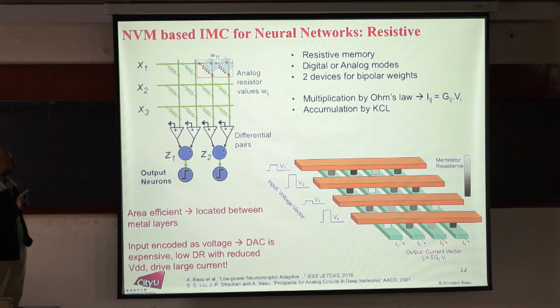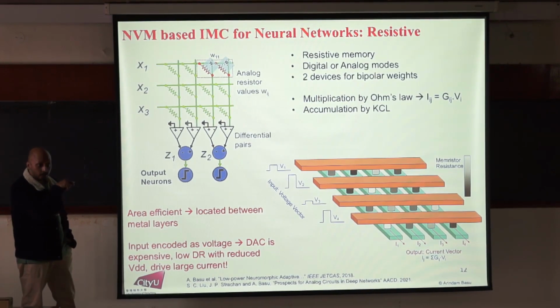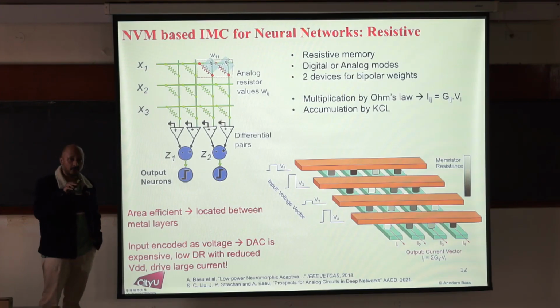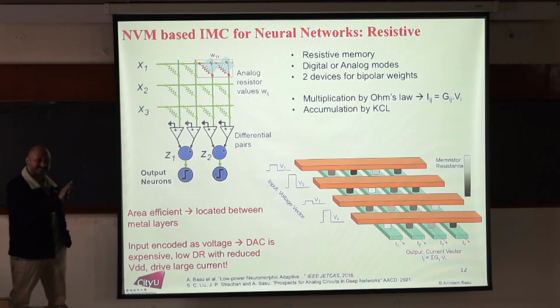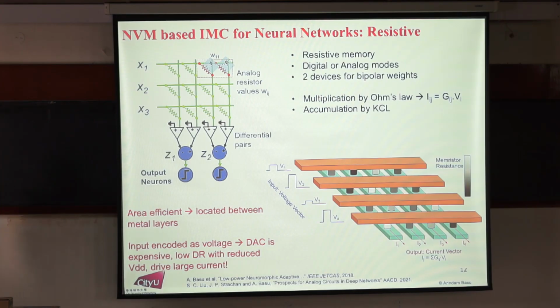And lastly, something that I did not talk about so much: because you have resistors, each of the resistors will draw current. That's how we are computing. So now these drivers have to push all of these currents through this entire row. That means it needs a very strong drive, and again it's not an easy design for this DAC. ADC will be a large part of my talk, so just hold on.